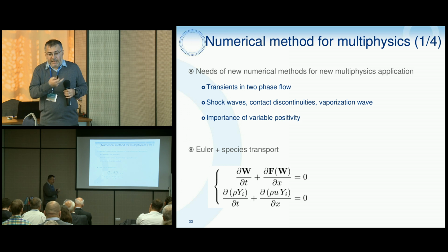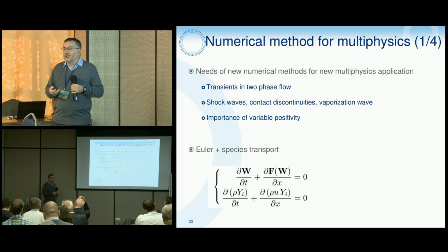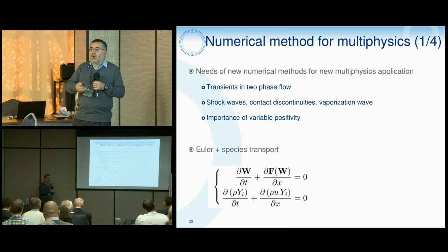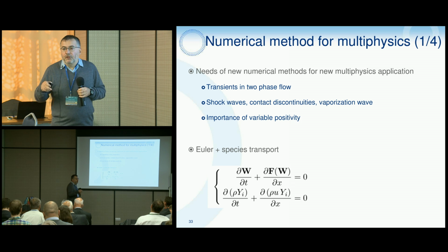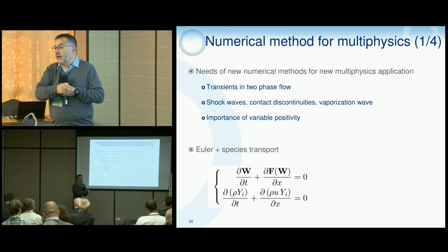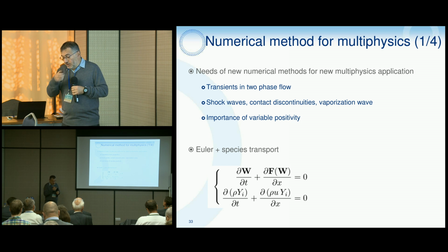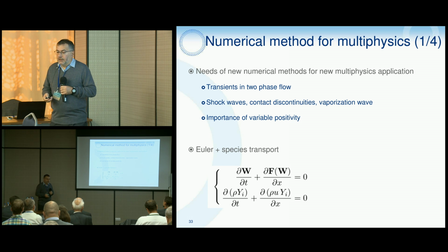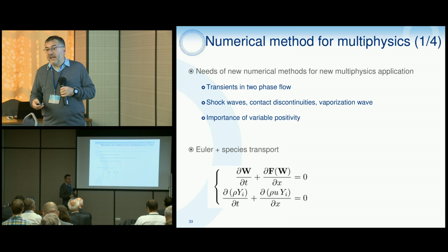And so I just talked about this new study, but we also have new developments. In fact, our industrial needs are evolving, because since the Fukushima accident, more and more studies are concentrated on safety problems. Most of the studies related to the nuclear power plant I talked about were related to the second loop, where we have steam flow, which can be considered like a monophasic fluid. But on the first loop, which, as I said, deals with pressurized, high pressure water, when we have problems, very often we have vaporization.